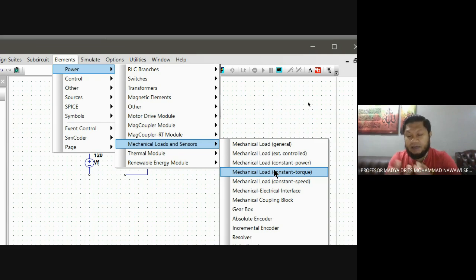And in that operation, when you have the motor at maximum voltage, rated voltage, and you reduce the flux. Remember, we have Vt over K flux. So if you reduce the flux, that is known as a field weakening operation. Okay? In that operation, we actually operate with a constant power load.